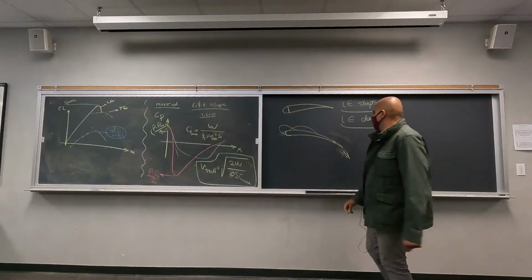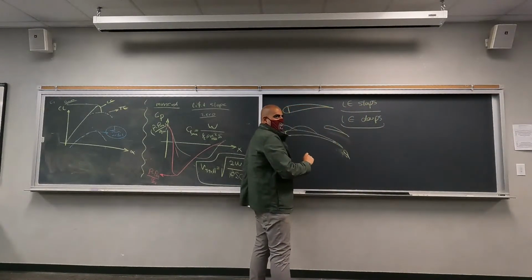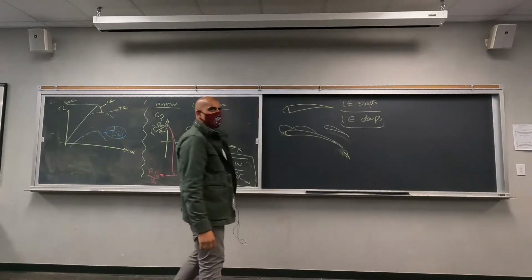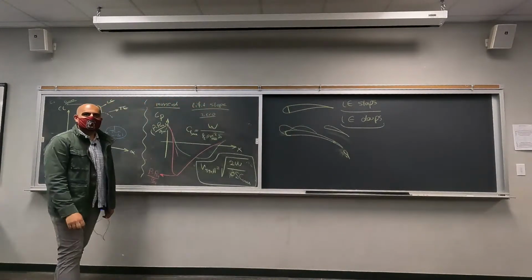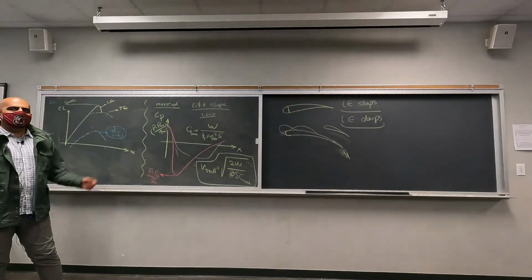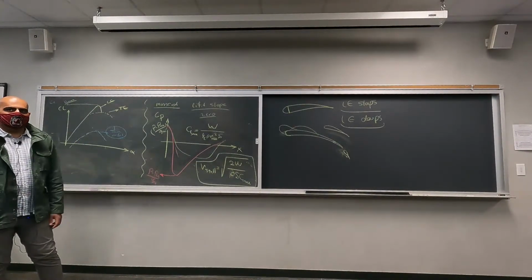Wings. So like this. I don't know how you would show it in this kind of form, but literally coming off the body like a wing, that would change the flow, because then it would also have, what do you call it, adverse flow behind it. But you are going to induce flow separation that way, right? Yeah. We want to delay the flow separation.